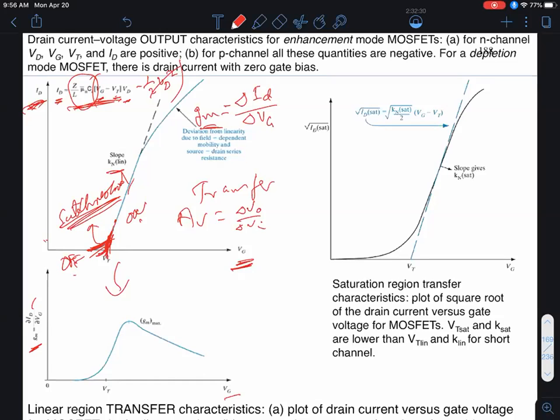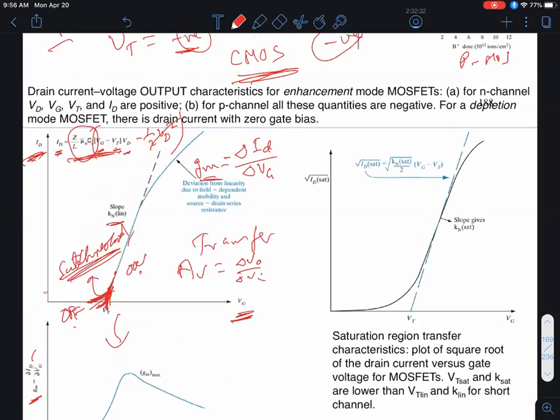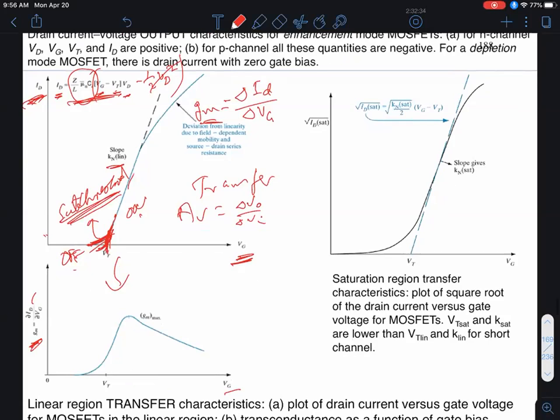Now, above threshold behavior is what I'm focusing on right now. You have to look at what I said is the transconductance, change of output current as a function of change of input voltage. And you take the slopes at different points. Here, the slope would be 0. And then the slope gradually increases. That's the point of maximum slope. So that's my GM max. But then you'll find that although this curve predicts a linear characteristic, a practical device will have the curve bending downwards. So it won't be this dotted line as predicted by this equation, but the curve as shown over here.